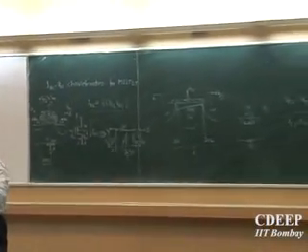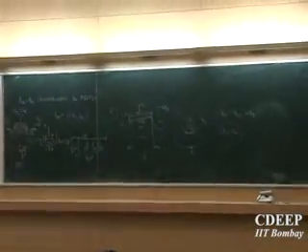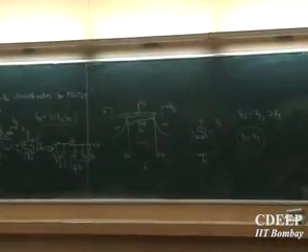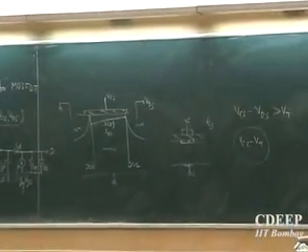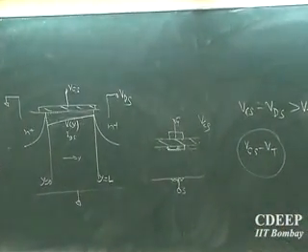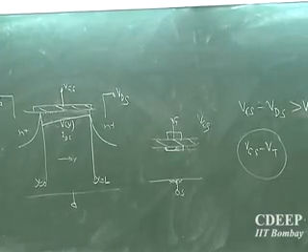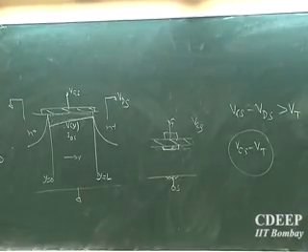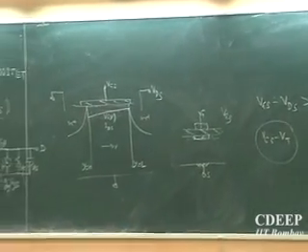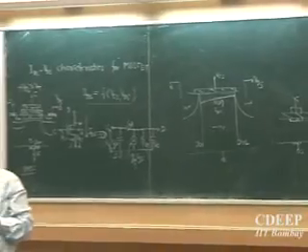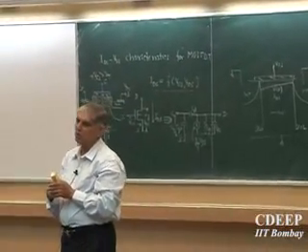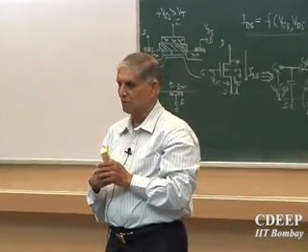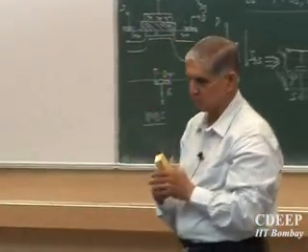All that I do is connect drain and source to ground, and that will act like a capacitor. The advantage with this MOS capacitor is that as the voltage changes, the capacitance also changes by a root law. The depletion layer is proportional to the root of voltage. We have seen the VGS characteristics. So that also acts like what? A varactor. So a MOS capacitor is also a varactor. So most MOS technology people do not use junctions, but use a MOS capacitor for their varactor requirements, variable capacitor.